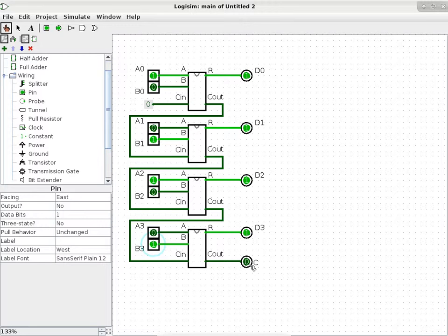On a breadboard, so how do you specify zeros and ones on an actual circuit board? Switches. Okay, you just use toggle switches and a pull-up resistor. So when it is not connected, it is a high. If it is grounded, it is a 0.